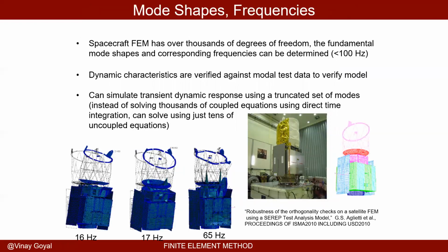Let me go to an application here really quickly. So, mode shapes and frequencies. One application that's typically studied is spacecraft finite elements. They can have thousands of degrees of freedom. The fundamental mode shapes and corresponding frequencies can be determined typically below 100 hertz. You can find those mode shapes and frequencies very nicely, and you want to verify that model. So one thing you can do is to calculate the dynamics, the eigenfrequencies, mode shapes, and then go from there, right?